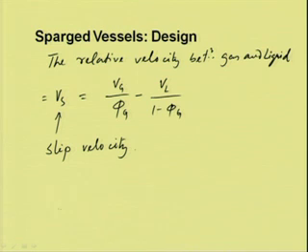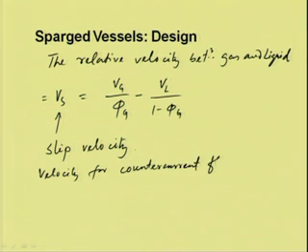From these equations we can also calculate the velocity for counter current flow, where liquid is falling from the top and gas is flowing from the bottom.